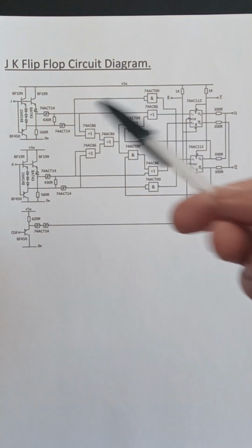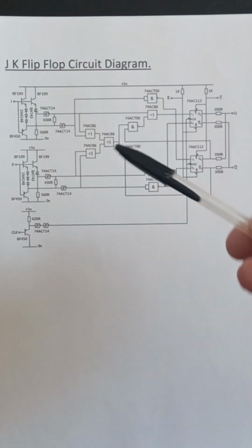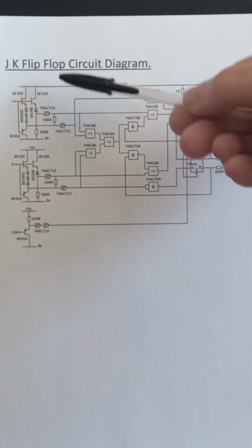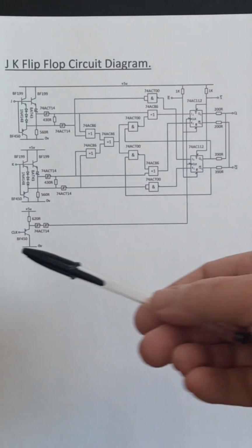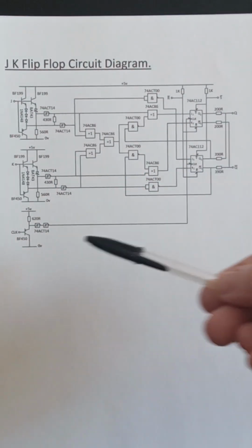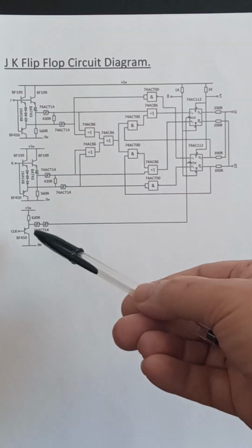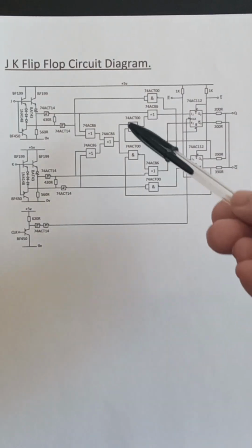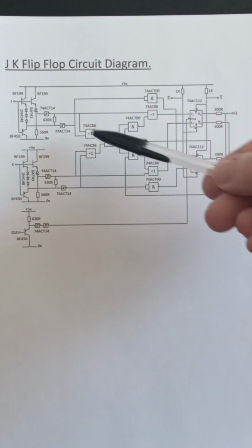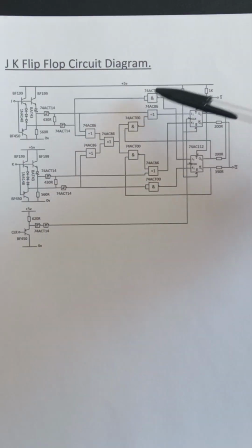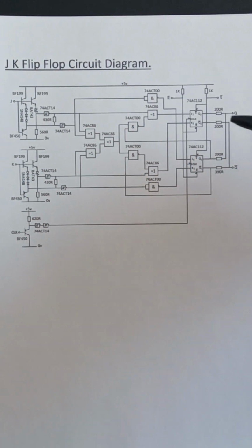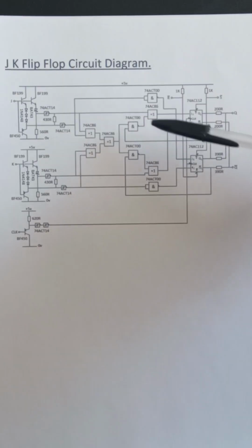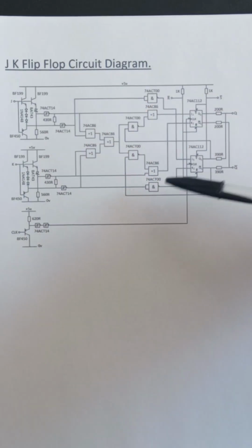So this is the circuit diagram for the Quaternary JK flip-flop. Here we have binary to quaternary and quaternary to binary conversion here and here. The flip-flops are clocked from the negative transition of a quaternary logic 1 to a quaternary logic 0. These are the exclusive OR gates here, NAND gates here, NAND gates here, and exclusive OR gates here. This is equivalent to a 4-input exclusive OR gate, and these are the expressions.